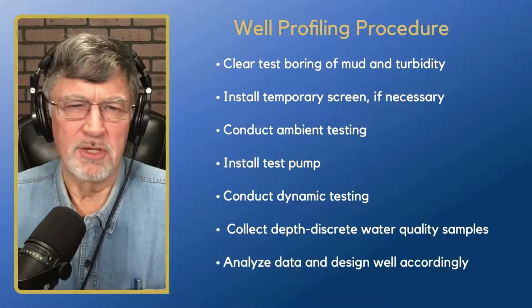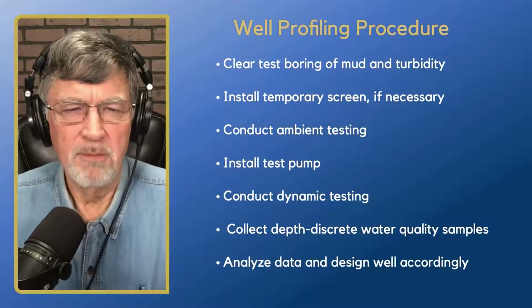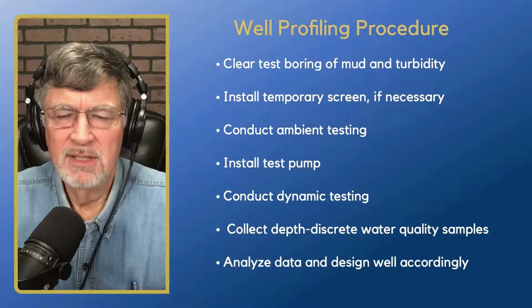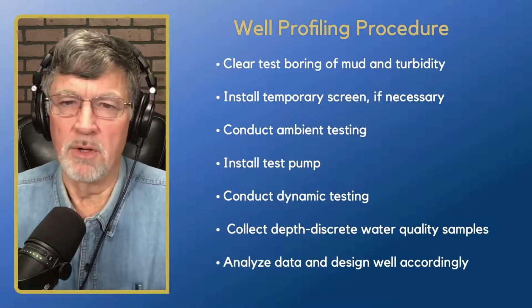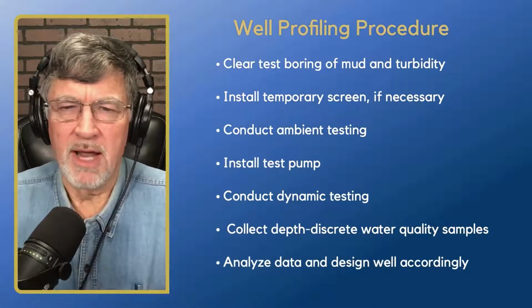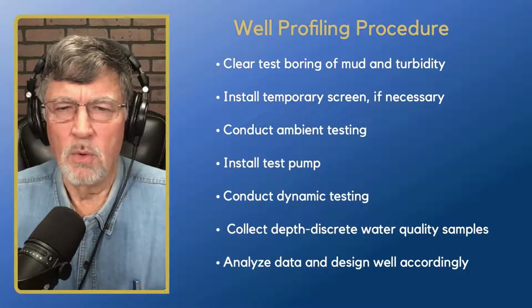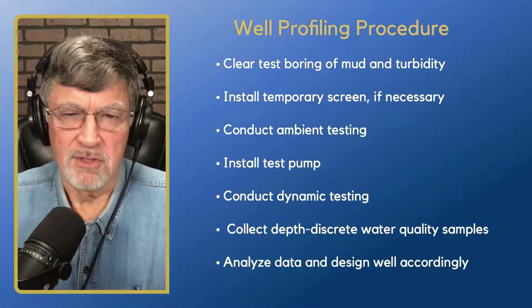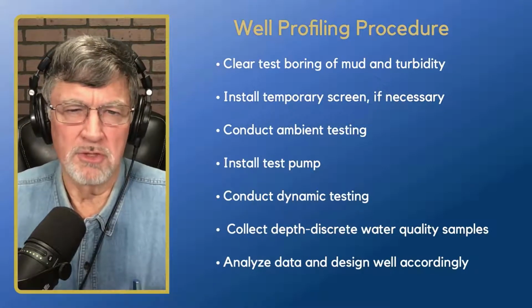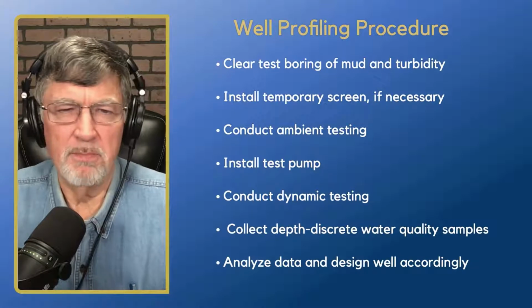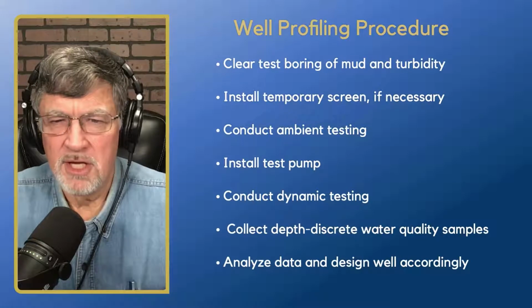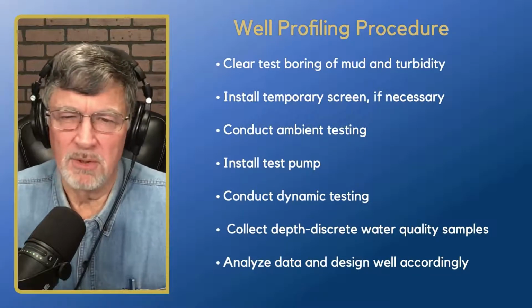We'll just use the temporary screen basically to hold the hole open while we do the testing, because we're going to be pumping and we just don't want that hole to cave in and then we've got to go back to the drawing board. So then we're going to conduct our ambient testing. We're going to install a test pump after that and then conduct our dynamic testing with the test pump in. So we're going to install our tooling. We're going to put in the test pump at our selected depth, and then we're going to do our testing, and then we're going to pull the test pump out and pull our tooling out.